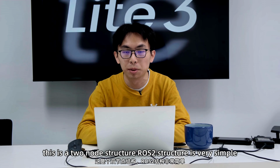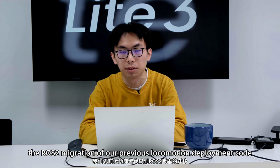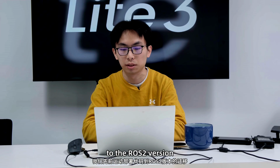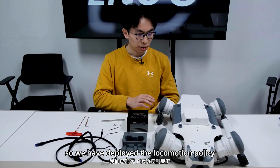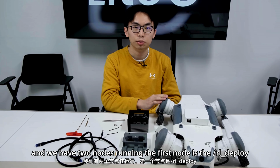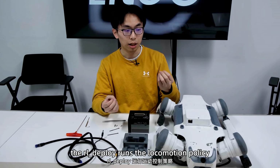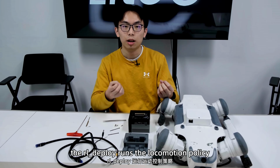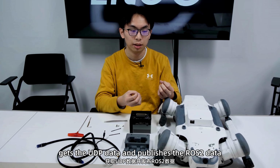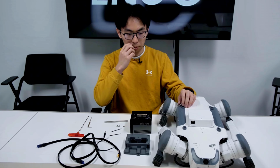ROS2 structure is very simple, and this part is the ROS2 migration of our previous Locomotion deployment code to the ROS2 version. So we have deployed the Locomotion policy, the ROS2 version, on the robot already, and we have two nodes running. The first node is the IO deploy, the other node is the transfer node. The IO deploy runs the Locomotion policy, while the transfer node gets the UDP data and publishes the ROS2 data. So these two nodes are running on the same computer, which is the robot, but this is not the point